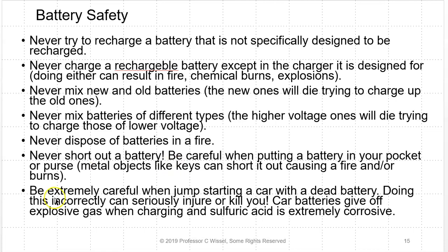That's really embarrassing. Be extremely careful when jump starting a car with a dead battery. Doing this incorrectly can seriously injure or kill you. Car batteries give off explosive gas when charging, and the sulfuric acid they contain is extremely corrosive. If you short out a car battery, the conductor that you shorted out with can literally weld across the terminals of the battery because they can produce so much current and they heat up the conductor so fast that it basically welds itself to the terminals. In that case, you can't get it off. Your best bet in that situation is to run and call the fire department.